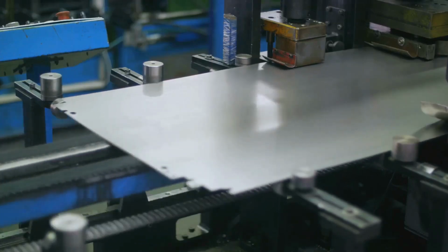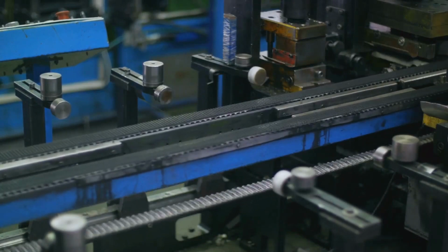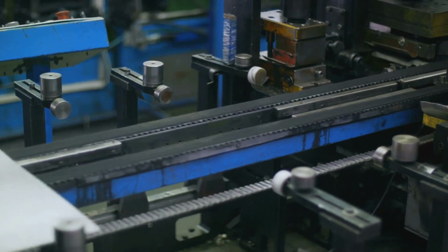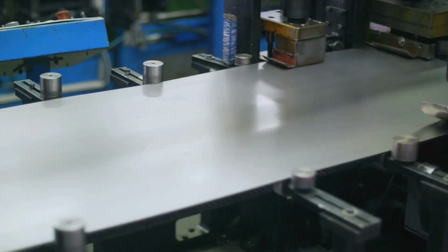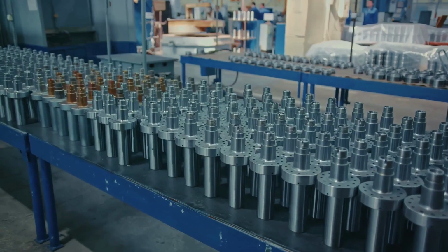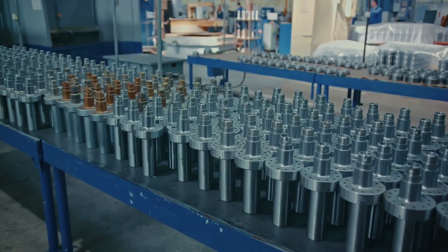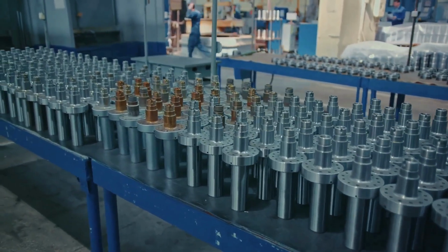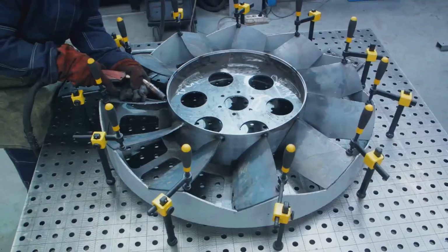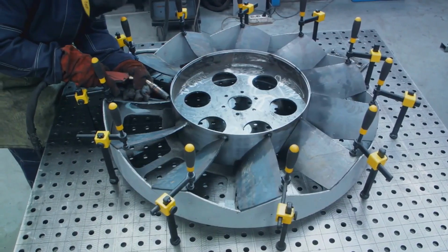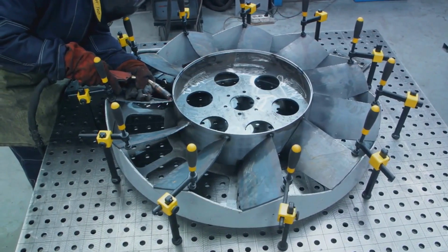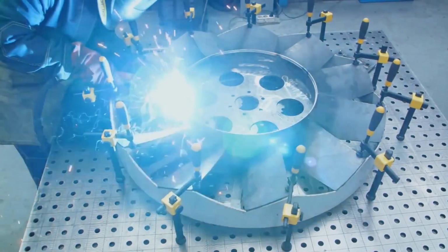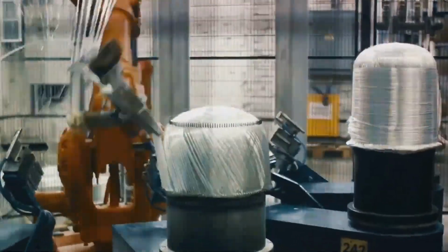But it's not just about the weight and cost. Aluminium is also resistant to corrosion, which is crucial when you consider that these aircraft will be exposed to all sorts of weather conditions. Next, we have titanium. This material is as strong as steel but weighs significantly less. It's used in parts of the aircraft that require high strength, like the engines and landing gear. Titanium is also highly resistant to heat and corrosion, which lends itself perfectly to the harsh environments of high-speed travel.